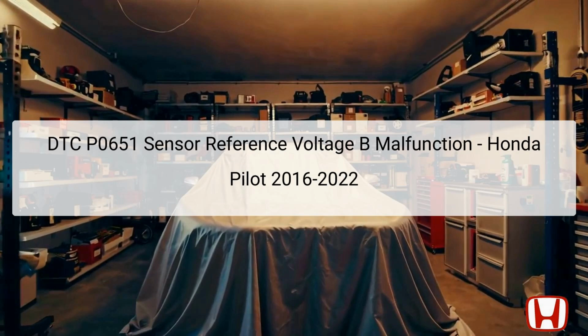The PCM monitors these voltage references to ensure that various functions, such as throttle position, engine performance, and other critical parameters, operate correctly. Anomalies in this voltage can lead to malfunctions that negatively impact vehicle performance. It is essential to diagnose this code promptly to maintain proper functionality. Diagnostic tools like the Honda Diagnostic System, HDS, play a crucial role in determining the exact nature of the malfunction, allowing technicians to replicate the problem effectively.